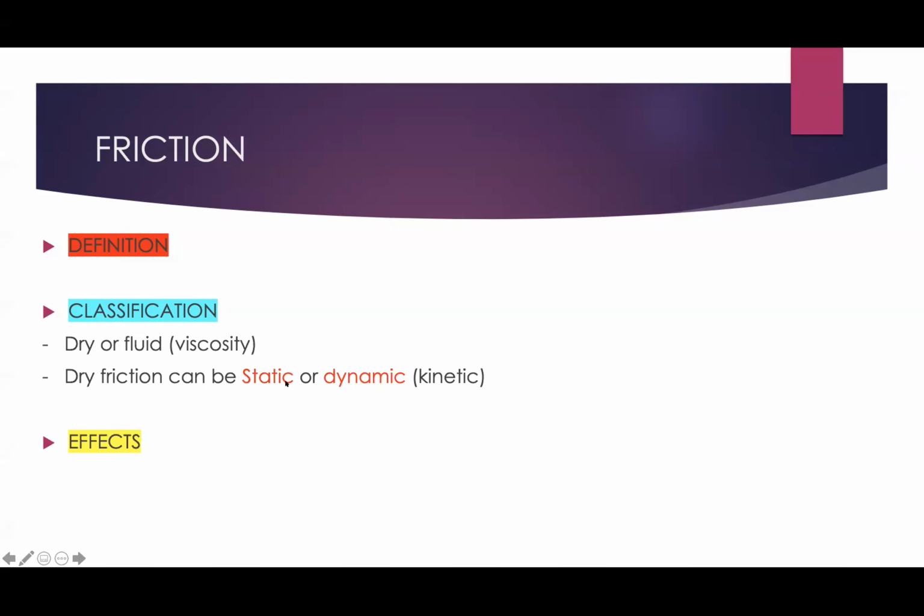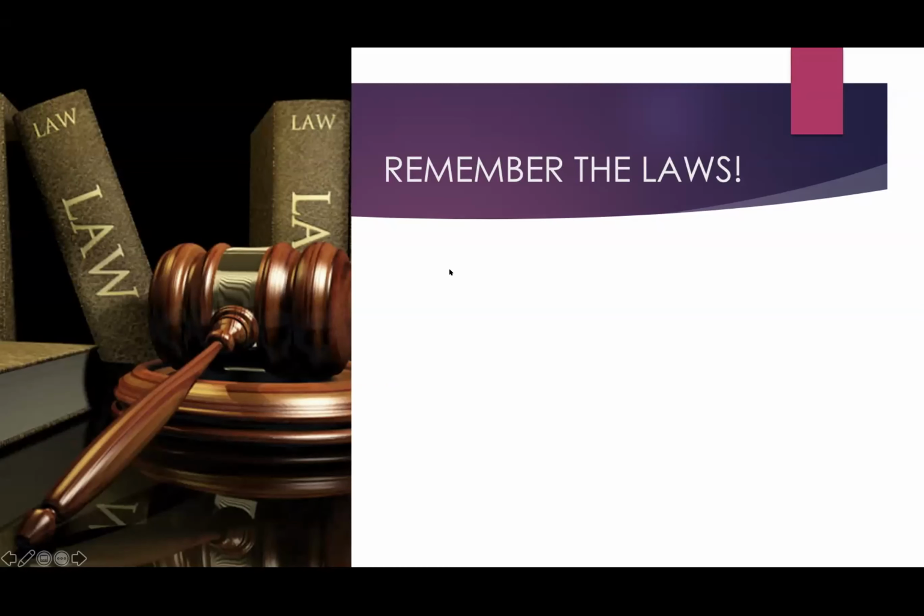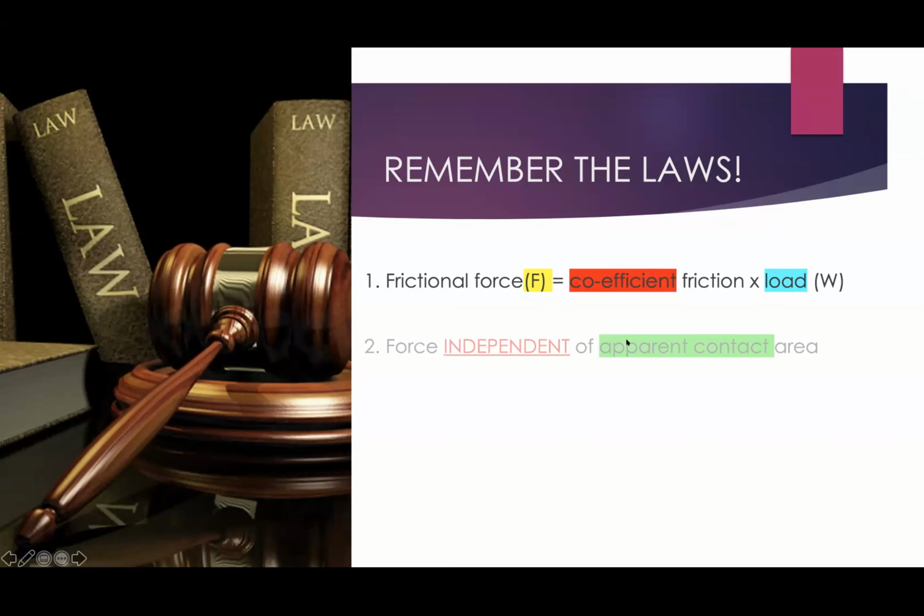In terms of the effects, friction basically causes loss of energy. It increases the amount of effort you need to move a joint and therefore the load on an implant. And ultimately, it's bad news because it increases wear. So there are some laws that you need to know, which were devised by Newton. The first one is that frictional force is equal to the coefficient of friction. Now, this is a non-variable thing, specific to the individual articulation, the coefficient of friction between two materials, times the load. Obviously, the load does vary. So if you get a higher load, you get a higher friction, okay?